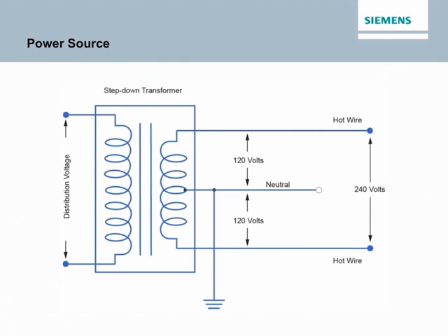The most common supply system used in U.S. residential applications today is a single-phase 3-wire supply system. In this system, the voltage between either hot wire and neutral is 120 volts, and the voltage between the 2 hot wires is 240 volts. The 120 volt supply is used for general purpose receptacles and lighting. The 240 volt supply is used for heating, cooling, cooking, and other high demand loads.